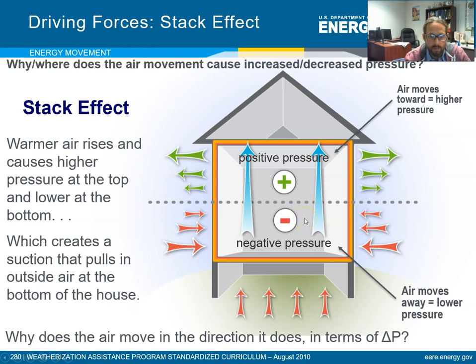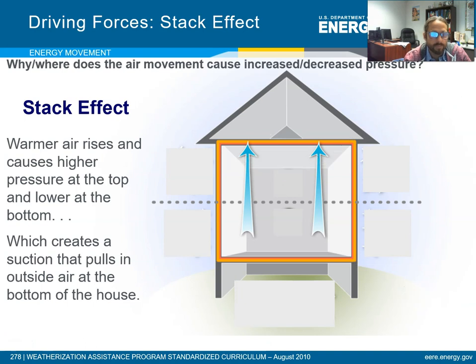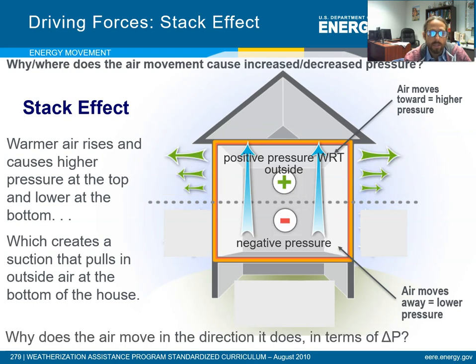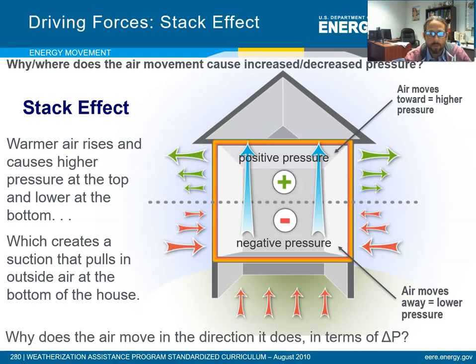So let's go back to the one, the air rises. So that creates a high pressure zone up high and a low pressure zone down low. And that consequently is pushing air out toward the top, away from the top, and pulling air in from the bottom. Okay? And so what you'll have then, this is really common in situations like this with the stack effect, the top, if it's not tightly sealed, is going to leak out at the top, especially toward the top. And some cold air is going to be leaking in the bottom. Okay?